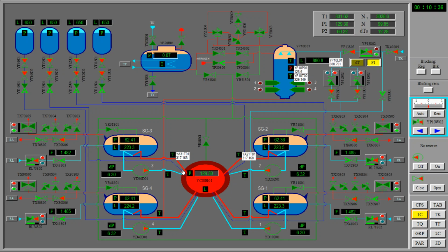So the pressure vessel, primary conduits, and the pipes going to the pressurizer are made of steel, and steel will dilate or contract depending on the pressure inside, and this will cause a small variation in volume that causes some flow of water in this pipe, which I assume is a very small pipe, because in normal operation it doesn't need to transport a lot of water.